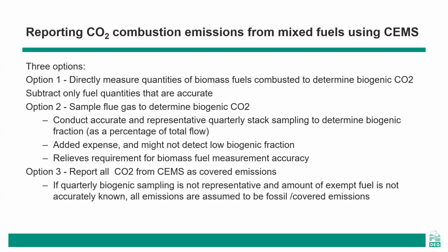The second option is to conduct quarterly stacked gas sampling. This relies on good fuel management and tracking so the ratio of biogenic CO2 in the flue gas can be applied to the total flow on an annual basis. The third option is that the biogenic fuels are counted as fossil-derived fuels. This is in the case that they are not measured separately or there is no data on the amount combusted.